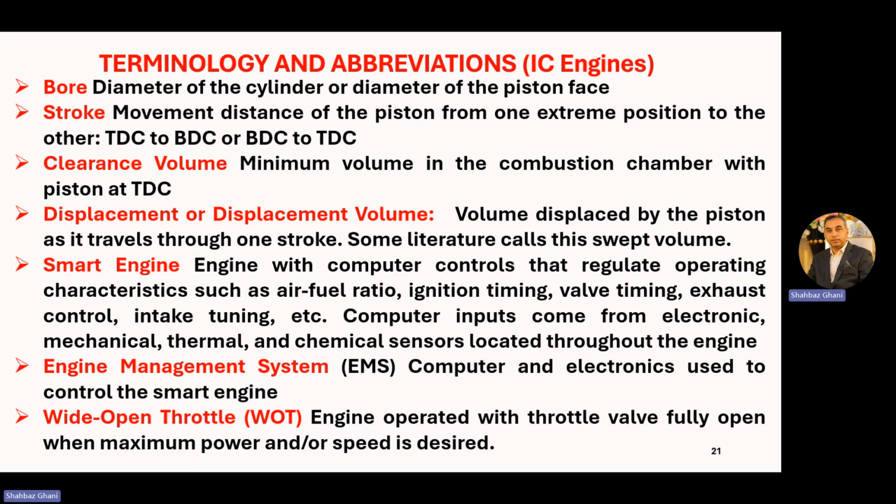Now, another term is smart engine: an engine with computer controls that regulates operating characteristics such as air-fuel ratios, ignition timings, valve timings, exhaust control, intake tuning, and extra computer inputs from the electronic, mechanical, thermal, and chemical sensors located throughout the engine. All the modern engines which are coming now are smart engines.